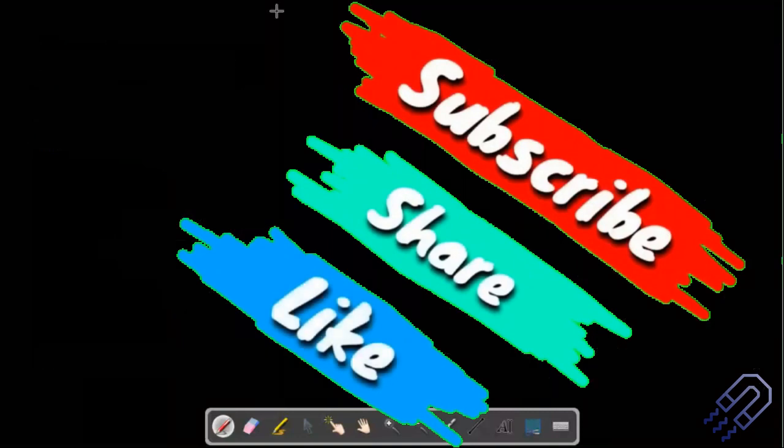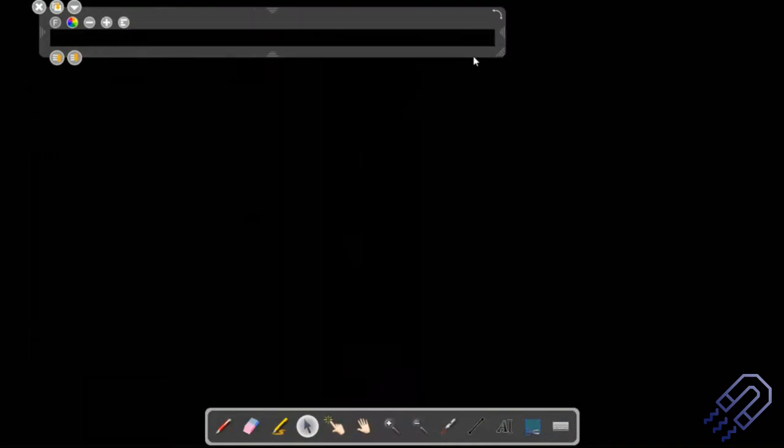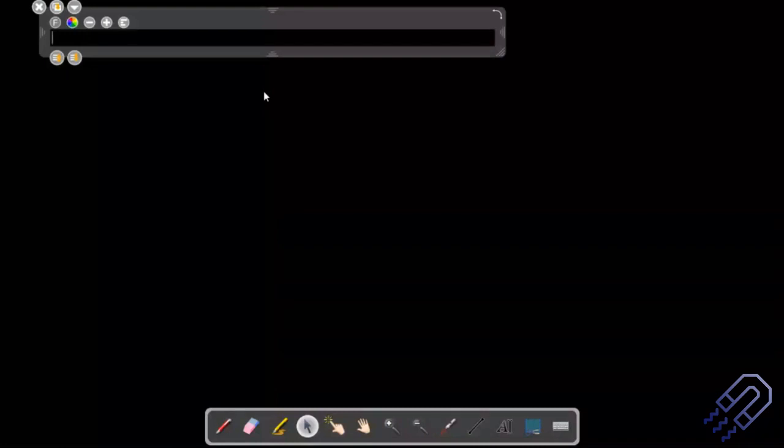And what happens is that after you show this diagram, you have to just write down a few points. So these are the points that you have to write. The saturation value point is important. And then secondly, you might also write down this. When input goes to positive, we basically have the output as plus 13 volt.